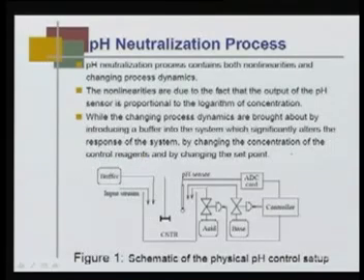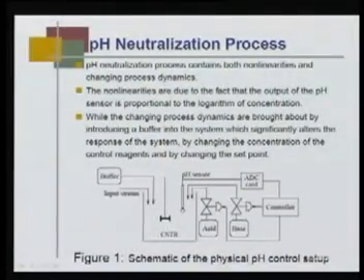What we have done here is that, you see here I have put only one sensor schematically shown, but in the actual experiment we have put these sensors in 3 different places in the CSTR, such that any kind of spatial non-uniformity can be taken into account by averaging the output of these 3 sensors placed in 3 different locations in this CSTR.